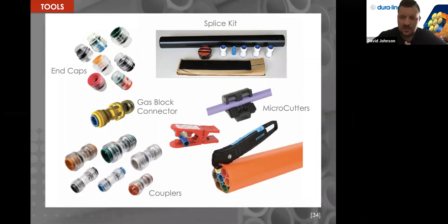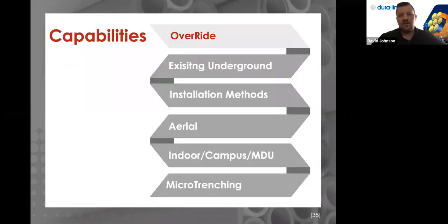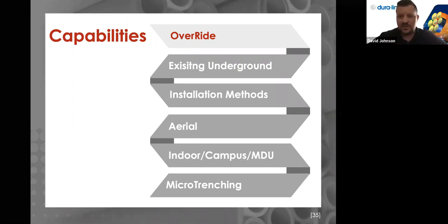So when you expose those inner microducts, it's the same thing as a standard conduit with 1.25 inch and so forth. So this is kind of where we're going to talk about that question that was answered earlier. We're going to go into a little bit of applications, why and where we use this product, and how it can help your network. And everything that we talk about here, we might be breezing through it a little quick, but it's really just to kind of tease you.